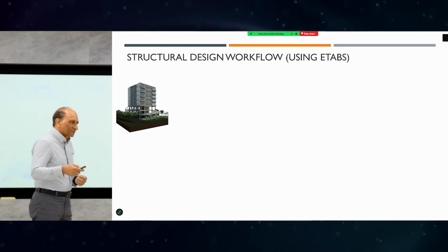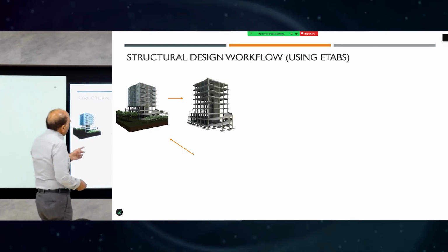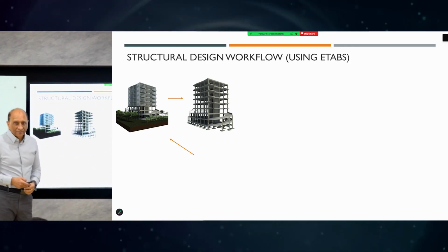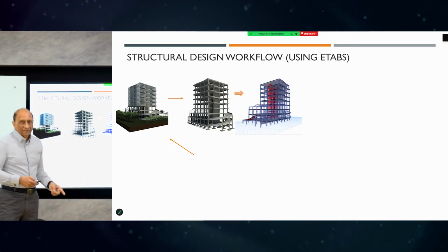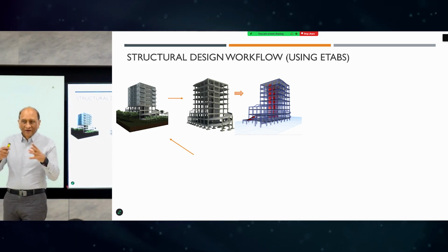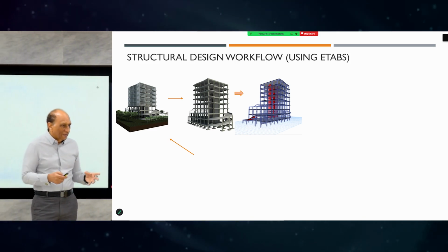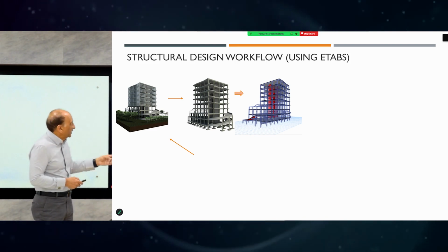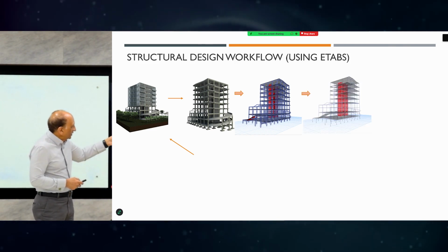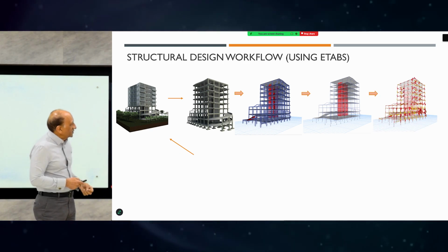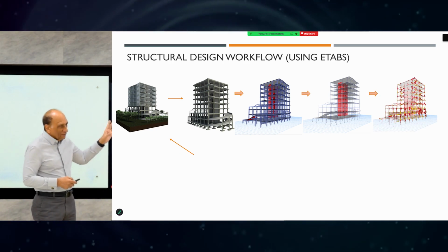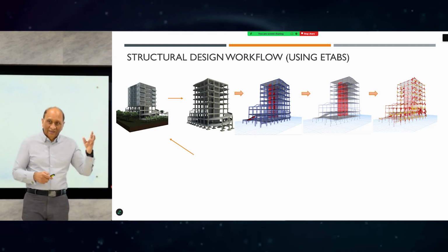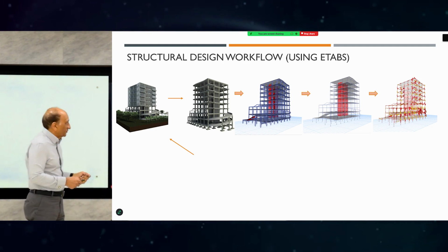So take a project and from there develop the structural system of that project, then create the finite element model. After you find the sizes, as I mentioned, you estimate the sizes. Based on that, you create the model in ETABS, and then you run it, do the analysis, and get the forces, all the design actions, bending moments, displacements, and so on.